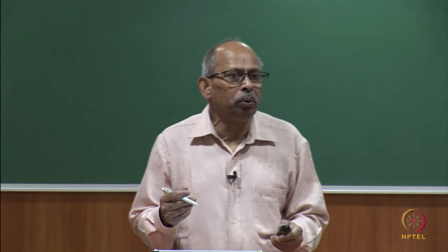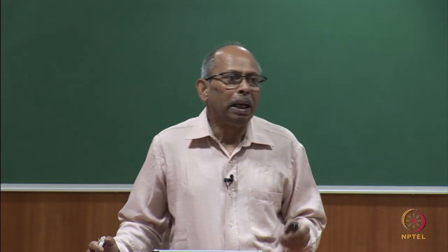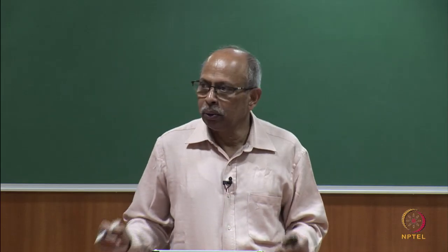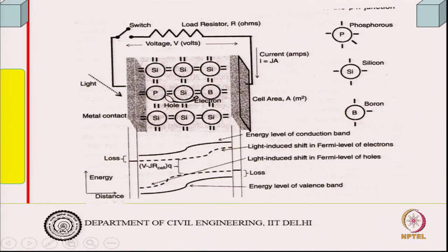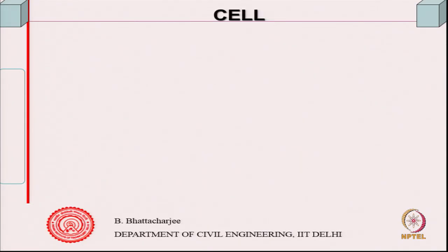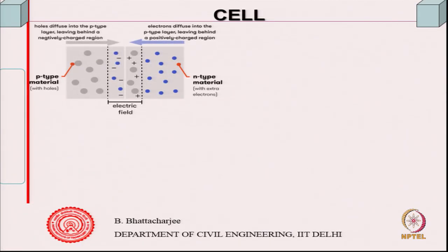It is something similar to what you would have remembered from the battery cell. When you measure open circuit potential, potentiometers or voltmeters, their resistance is very high, practically no current passes. So, therefore, it gives you the available total voltage, but the moment you short it or connect it through a load or otherwise, some EMF will be lost in driving the current through this. So, that is what we looked into in the last class.